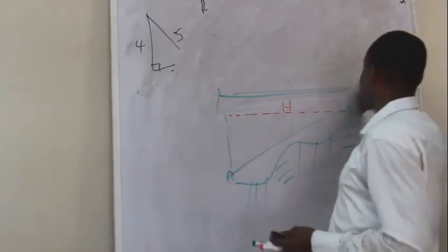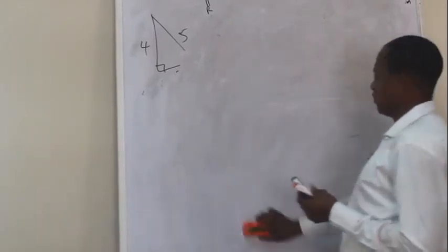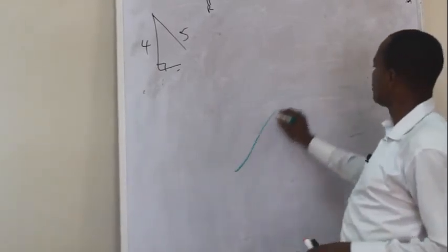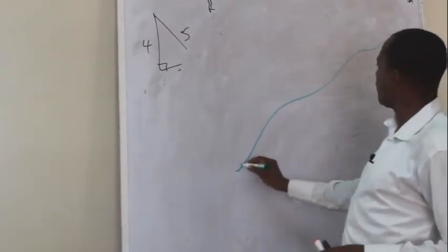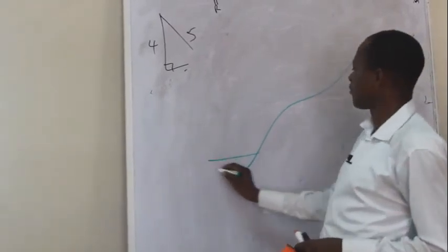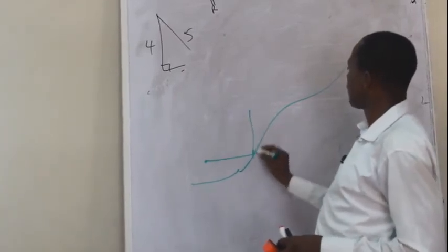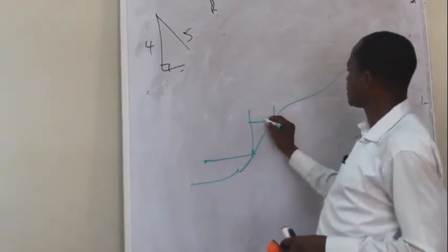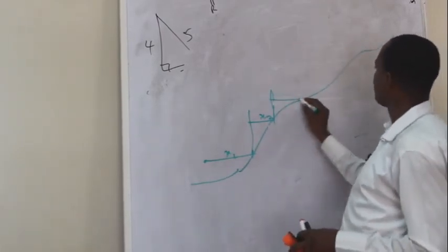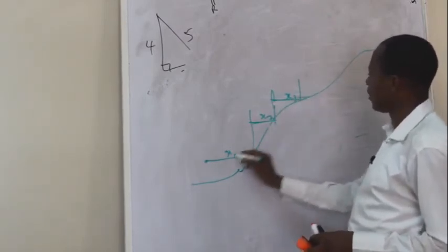And then look at this particular method of doing that. You can carry out step chaining. Instead of measuring like that, you can start to measure like this, maybe from a particular point here, and you measure from here again. This is horizontal, let's call it X1, X2. From this point again, measure X3. You can see now these are horizontal, horizontal, horizontal.